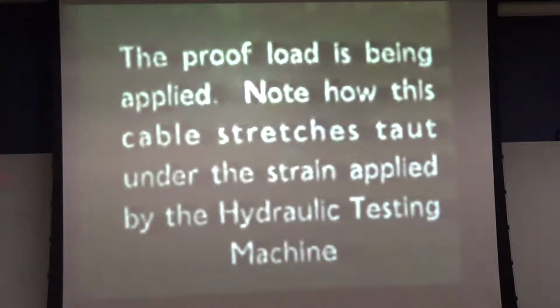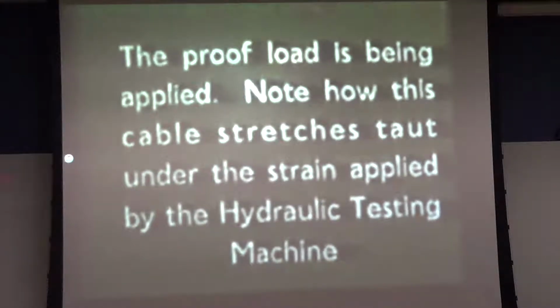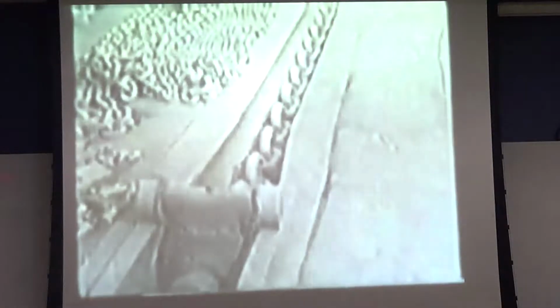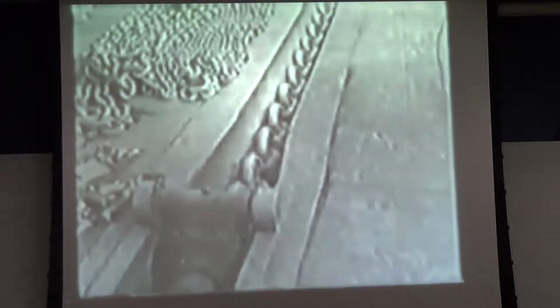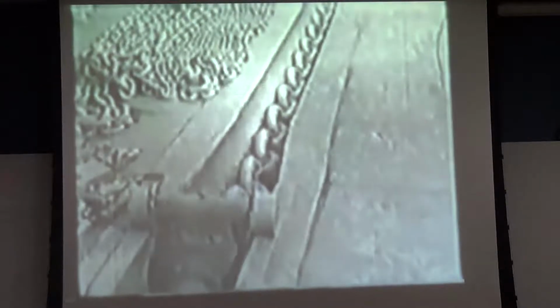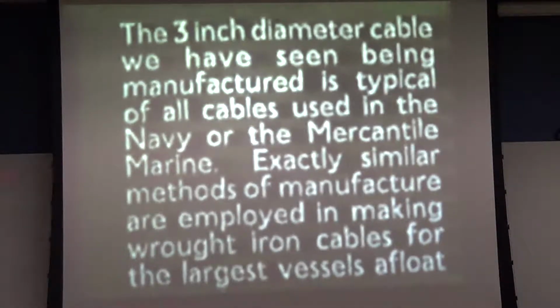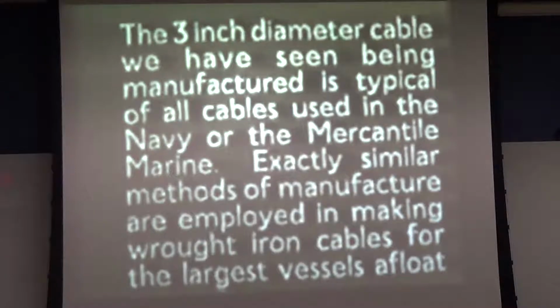And what they're doing is they're listening for the kind of sound it makes. And if that weld is a good weld, you'll have a high-pitched ring. But if it's not a good weld, it'll go thunk. So I was talking with the chief metallurgist for the American Bureau of Shipping, who I know, about this. He says, oh, we still test anchors today basically the same way. They pick them up and they drop them. And if they ring, they're good.